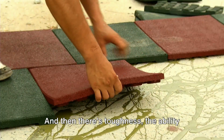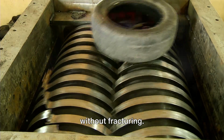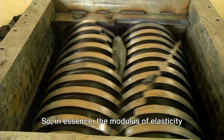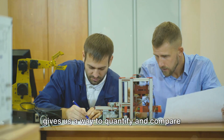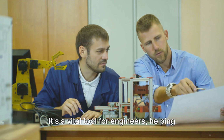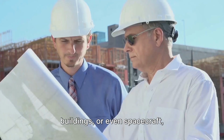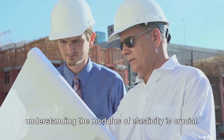And then there's toughness, the ability of a material to absorb energy and deform without fracturing. A material like rubber might not be very stiff, but it's tough because it can absorb a lot of energy before it breaks. So in essence, the modulus of elasticity gives us a way to quantify and compare these different properties. It's a vital tool for engineers, helping them choose the right materials for the right applications. Whether they're designing bridges, buildings, or even spacecraft, understanding the modulus of elasticity is crucial.